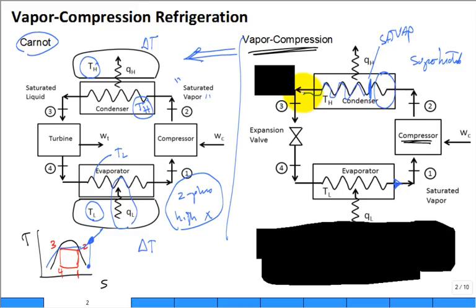Now, right away, the majority of the heat is transferred out of the refrigerant while it's at TH, but some of the heat's transferred out where the T2 is greater than TH. It's got to cool it down. So you can see that here. You got to cool it down before you can start to condense. So state 1 is pushed over, 2 is over here on a TS diagram. We still come out of the condenser fully condensed.